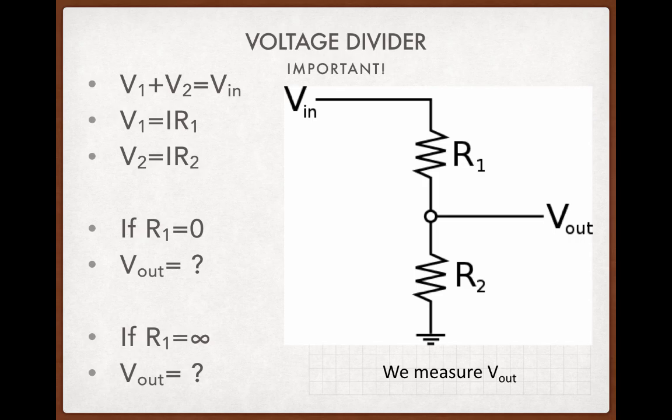Okay, so how are we going to use this very simple Ohm's law? Well, basically we use it in a voltage divider type network. Here we have a voltage applied to R1 and R2, and we tap off the middle between R1 and R2, and we get a voltage which is related to the ratio of resistors R1 and R2. So we add up the resistance of our series circuit, R1 plus R2. We calculate the current through that circuit, V in divided by R1 plus R2. We then need to know what the voltage drop is across R2. That will give us V out with respect to ground, the voltage across R2. So we have our current through the circuit, we multiply that by R2, and that gives us V out. So that's where our voltage will be read from.